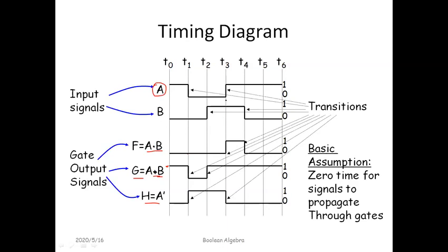Then at 3, there's a transition on the input signal from low to high. Then it remains high up to the end of our timing point. Whereas on the output, at 3, it transitions from high to low, and it remains there up to the end of our timing point. Okay, so these timing diagrams are very, very important. We need to master these timing diagrams, as they are very, very important in our study.